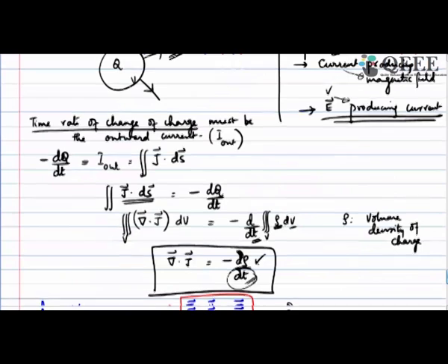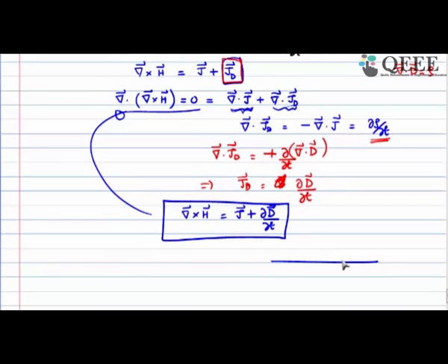So it means, we said earlier that as for a current carrying conductor, there is a magnetic field around it, and the way it curls is decided by the strength of the current. The addition is that in addition to that, it is also decided by del D by del T, which is nothing but epsilon del E by del T. It simply says that if there was a time varying electric field, it also depends on what is the time variation of this electric field. That is the additional contribution, that is the physical secret.